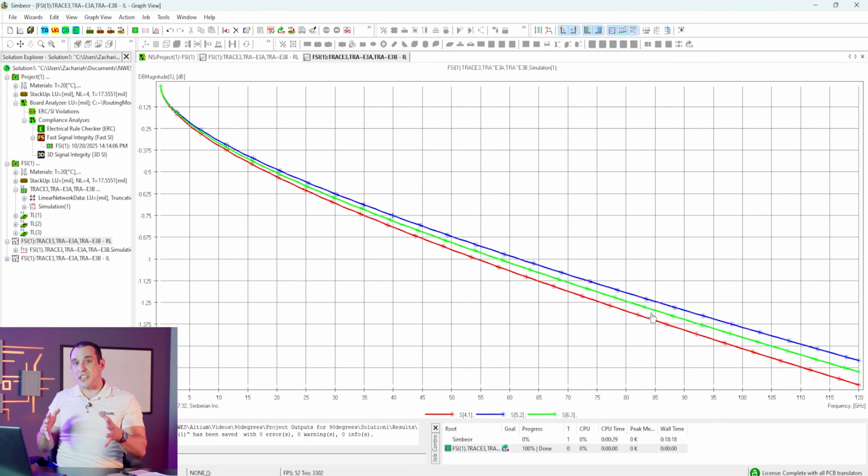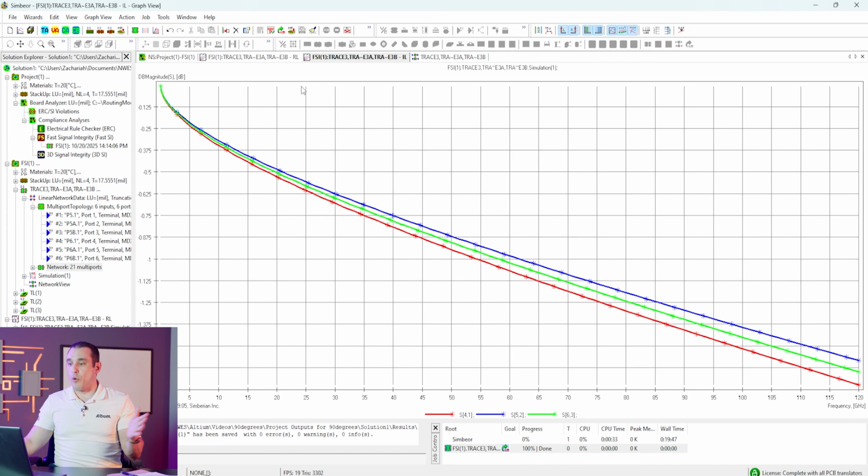Now this is interesting because the conventional wisdom around RF routing is that you need to have these right angle bends in these traces in order to have minimal return loss, and nobody says anything about the insertion loss. But what we actually see is the opposite. The effect seems to be insertion loss driven and not return loss driven. Very interesting. Now you might be asking, why exactly do we see these very slight differences in the insertion loss?